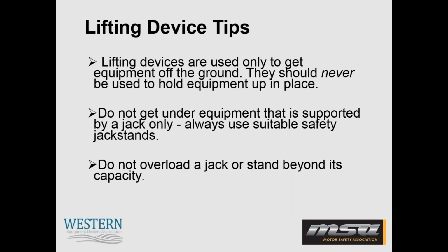Another lifting device tip is lifting devices are used only to get the equipment off the ground. They should never be used to hold equipment up in place. So once you utilize a jack to lift the equipment up into place, you're supposed to replace that jack with jack stands. And we sometimes see that this step gets overlooked and people leave the equipment sitting on jacks. And you need to get that jack out and have your jack stands holding that equipment into place.